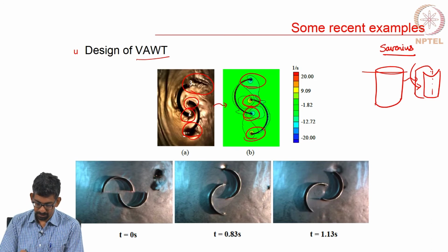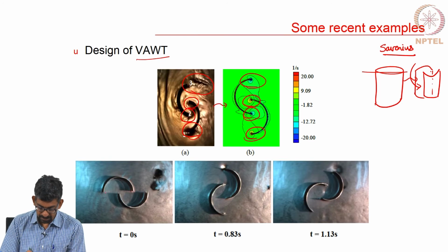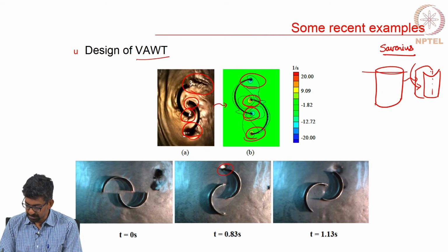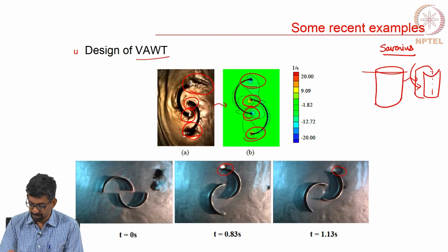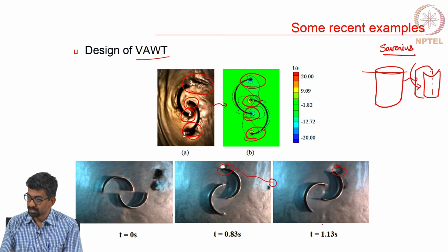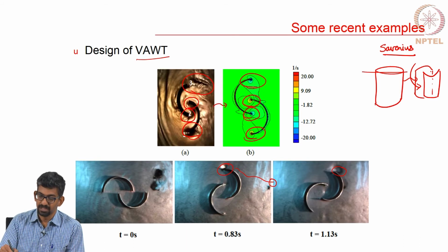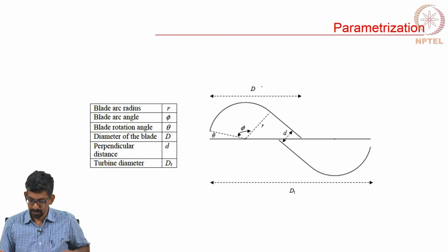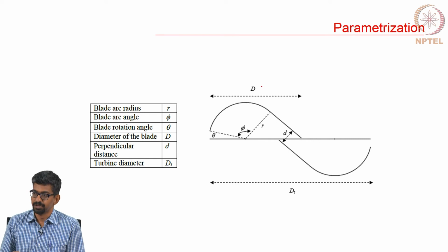And there is something called the Strouhal number. So, we are seeing that when the vortices are created, you can see the vortex is created and then it is leaving. So, the vortex will travel like this and then we will go and capture. So, within 1 second or over 4 seconds, how many vortices are being shed? Is that the same in the computer model? That is something that we wanted to check. But this was the initial benchmarking.